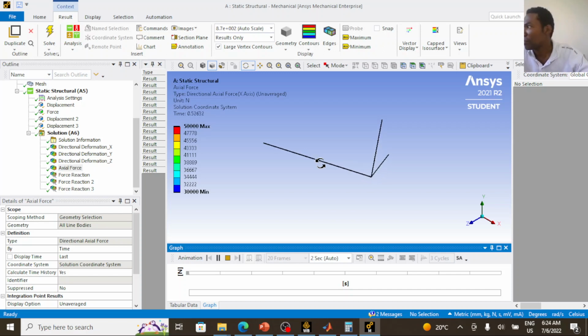You can model more complicated structures than this, like roof truss, electric mast, but this is just an explanation of the step-by-step procedure of going about modeling a 3D truss system on the ANSYS program. So we have come to the end of the truss problem now. I've covered plane truss problem and 3D truss problem using the finite element procedure on Matlab and on ANSYS.